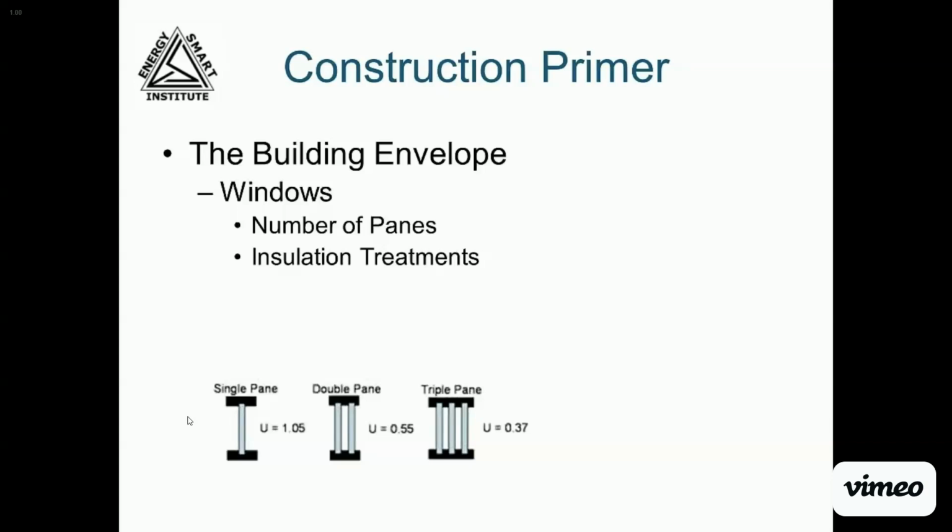just a rough equivalency. The area of building envelope wall that's taken up by the windows will have a much lower R value than the rest of the wall area, and so will be much less resistant to heat transfer. However, the materials used in the window frame, the coating that can be placed on the glazing, and gases that can be used to fill the space between the panes all impact the energy efficiency of the windows.